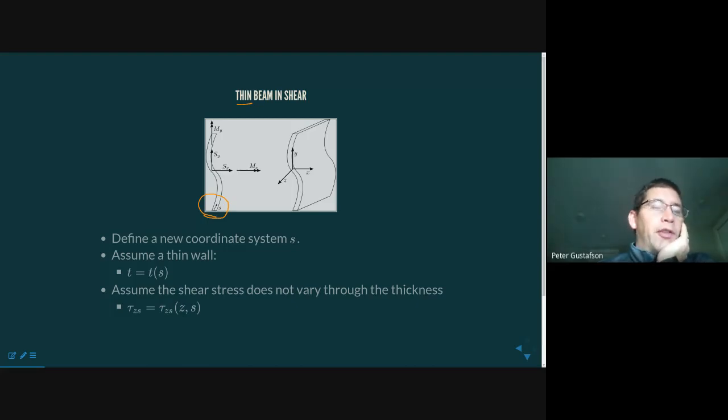I would say that those numbers that we used previously, 5, 8, 10, are again some good guideline numbers to use. The theory that we will now develop is in fact quite accurate when the wall is thin. However, it gets worse as the wall moves away from being thin. And so again, these are all relative numbers.